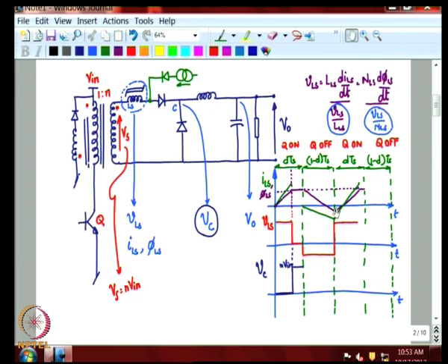And how can the starting point be different? By giving different negative slope rates of the current by adjusting the value of the current source, the current which is driven during the off condition, the flux can be brought down to different values, either to 0 or a bit less than 0 or still up.